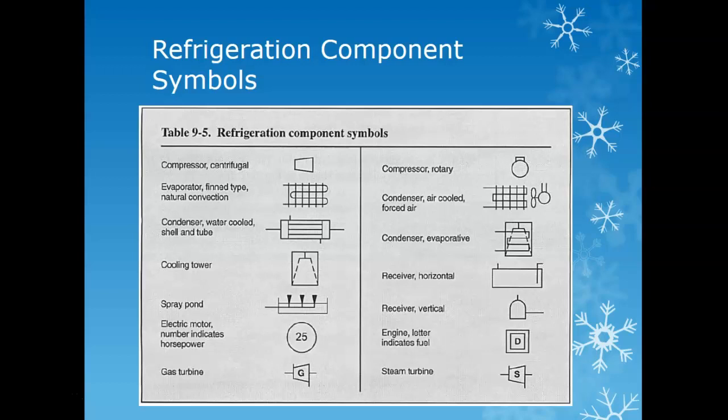And what they do whenever they make these is that you have a line for the whatever it is to run through it. You got fins on either side of these lines. And the fluid passes through those. It's moving back and forth. Those fins are what pull and dissipate the heat from those lines. Okay? Does that make sense? And yes, I do watch a lot of How It's Made.